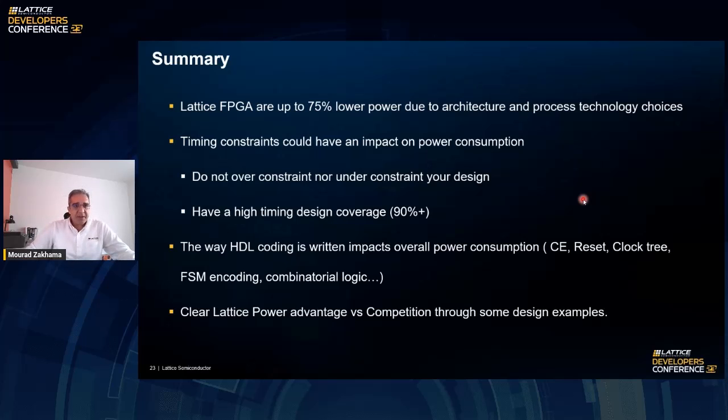Sometimes we don't think that timing constraints could have an impact on power, but we've seen that in fact timing constraints are important in terms of power optimization. So make sure that you have high timing constraint coverage for your design, and not under-constrain or over-constrain your design, making sure that you have your timing constraints set properly.